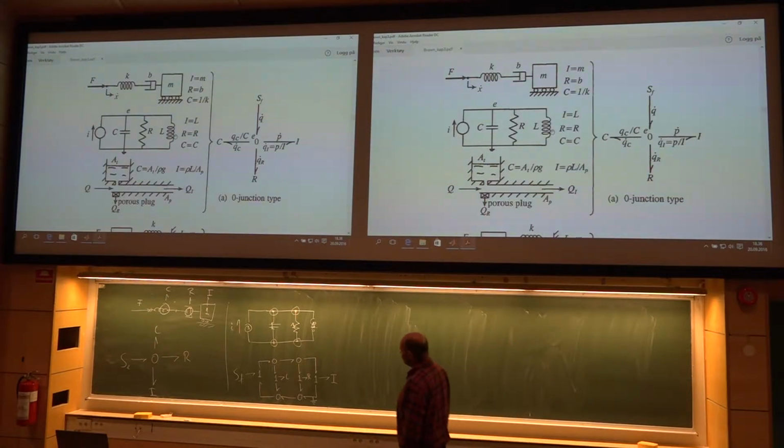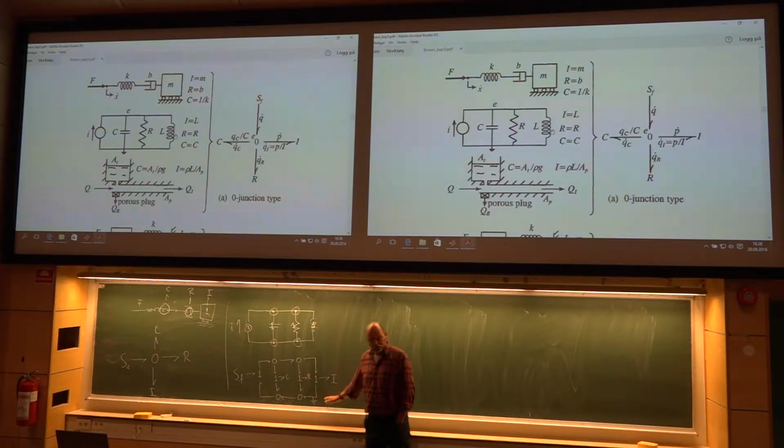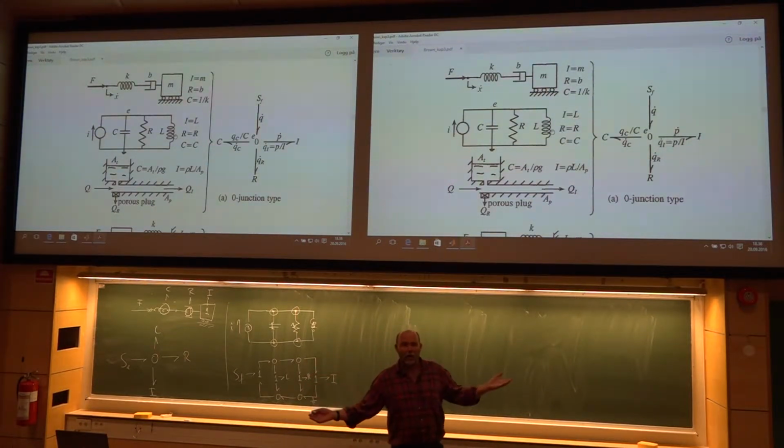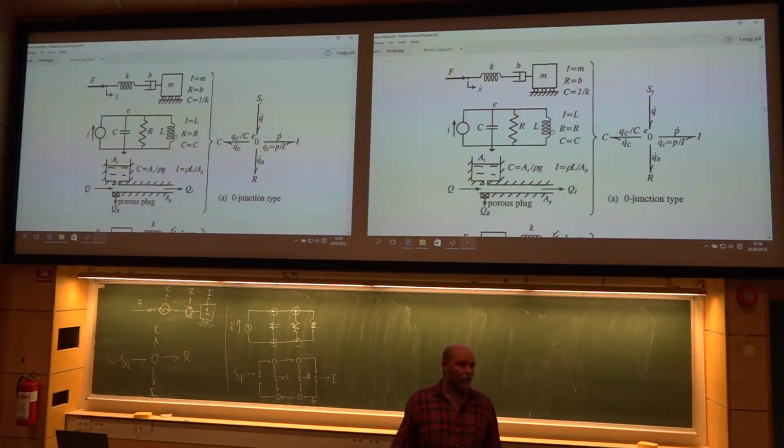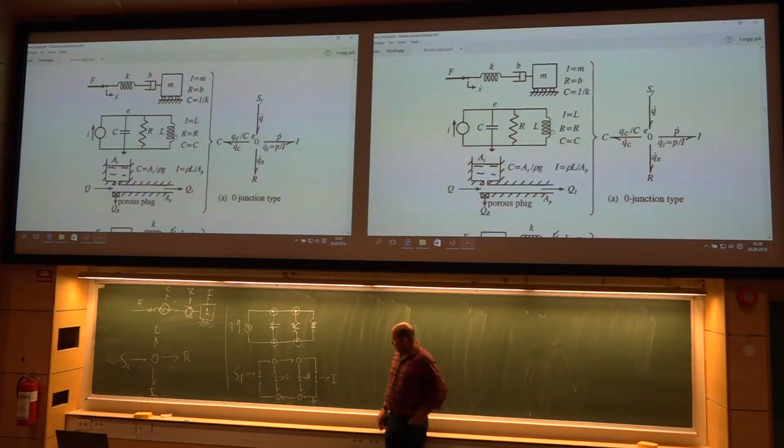For fluid systems you do it in the same way, but then with the pressure, saying that you have an outlet out to the atmosphere, and we always calculate with gauge pressure, not the absolute pressure. So we sort of subtract the atmospheric pressure, meaning atmospheric pressure equals 0 pressure.